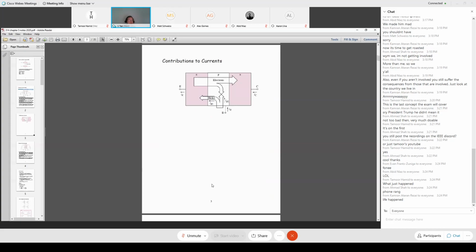This diagram just graphically illustrates what I previously said. Under forward active mode condition, the electrons inject into the base, diffuse across the base, and then are swept by this space charge field into the collector. So the majority of electrons emitted from the emitter end up at the collector. And the holes in the middle P region, moving this way, also contribute to the emitter current, but it's only two orders of magnitude lower, because you have two orders of magnitude higher amount of electrons compared to the amount of holes here. So these are very tiny, although they do contribute, this amount compared to this amount.